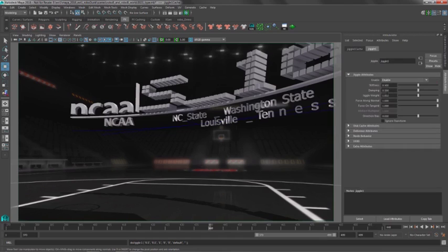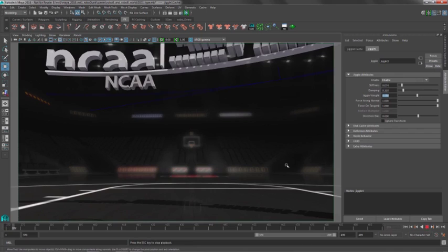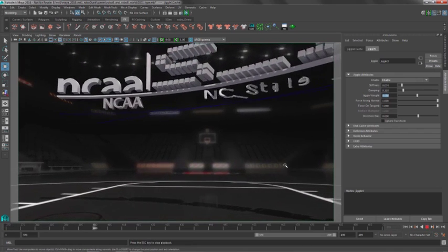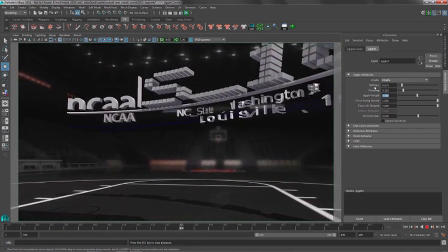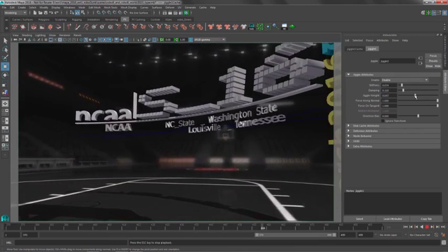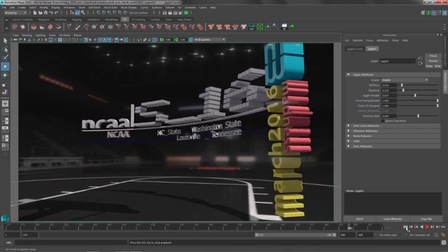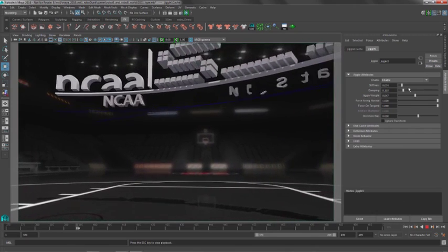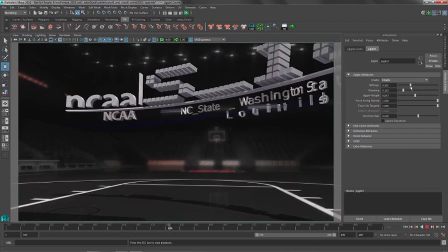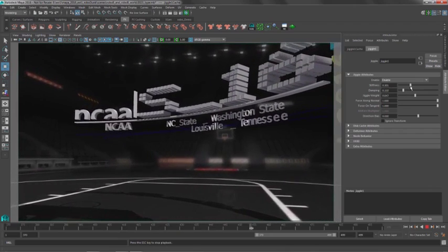We're going to change a few of the default attributes. A jiggle value of something like 0.95 will be pretty good, and we're going to drop the dampening way down and the stiffness way down, and we'll play this back, and you'll see it's going to come in, and it's going to have this cool wavy effect now, and I can adjust that. I can maybe drop the jiggle weight down a little bit further, and we'll see what that looks like the second time through here. Maybe you make it have a little more stiffness, but it gives you this nice layered effect.